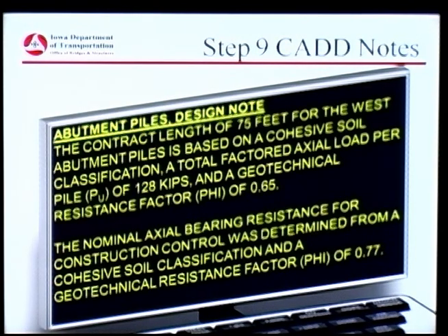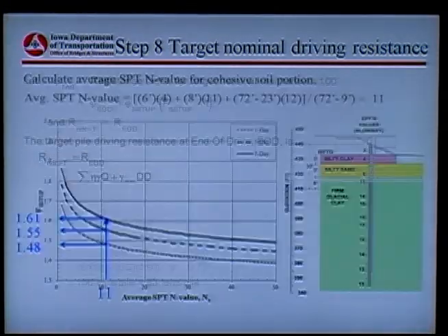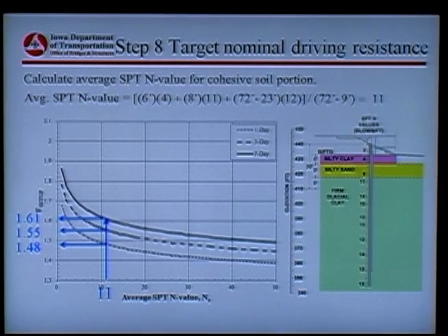So now we need some design notes here. The other thing I wanted to point out, just so that it's clear, back here on this setup, remember about the pore water pressure? Remember that plot from one of the earlier presentations, that when we first drive the pile, we have a pore water pressure dissipation, and with that pore water dissipation, we're getting this pile setup.